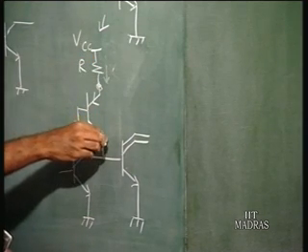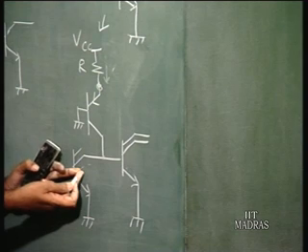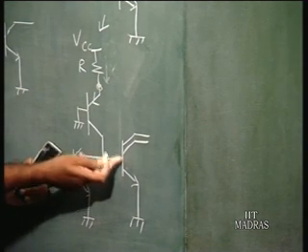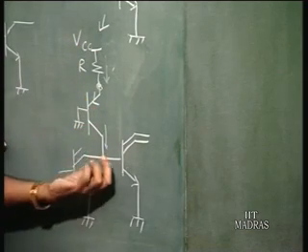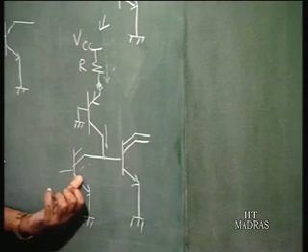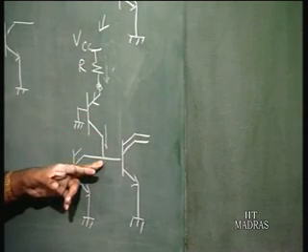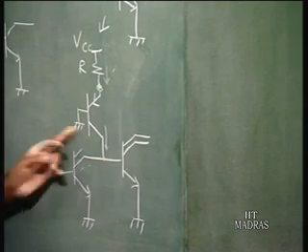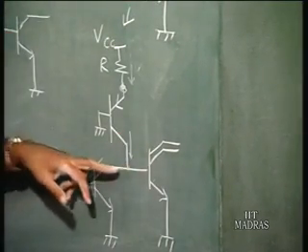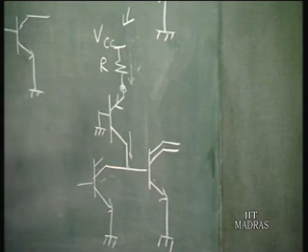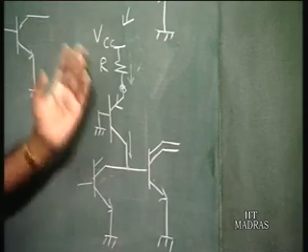So, the current which flows here is going to flow into the collector of this transistor. If this transistor is off, this output point is going to rise high, and this current which is flowing here goes into the base of this transistor. So, basically the current from the current source either flows into the previous transistor if this is conducting, or it is going to flow into the base of this transistor, making this transistor go to saturation. So, the voltage at this point is going to be either 0.2 volts if this transistor is in saturation, or 0.7 volts if this transistor is conducting. So, the voltage here changes by a very small margin, 0.2 to 0.7 volts, and the current either flows here or there. We shall see later how you can realize the different logic circuits using this.